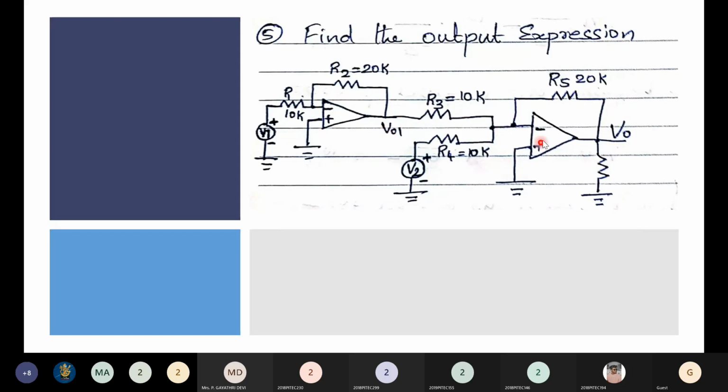second one. Now, this is the second op amp. You can see it has an input here. The output of the first circuit is the input of the second one, and one more input is also given through a resistor to the same terminal. I already told, is it not, when you have multiple inputs to the same terminal, either inverting or non-inverting, it means it is an adder circuit. So you have two inputs directly given to the inverting terminal of the op amp, and therefore this is an inverting adder circuit. Non-inverting grounded, you have a feedback. See, so this is an inverting adder.